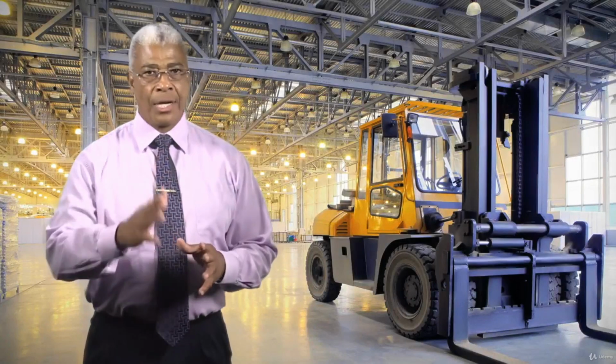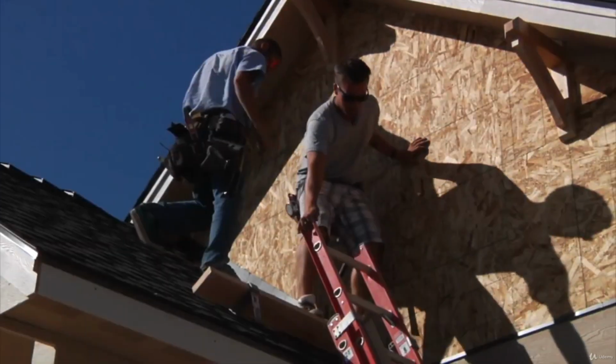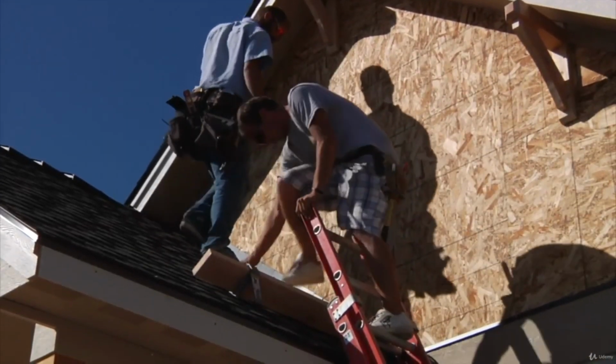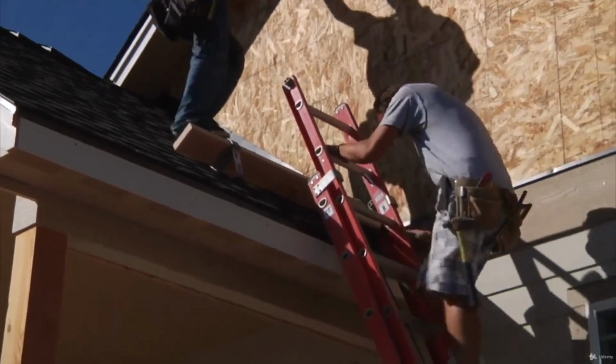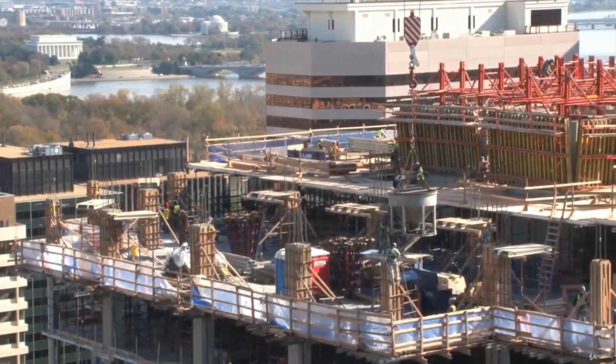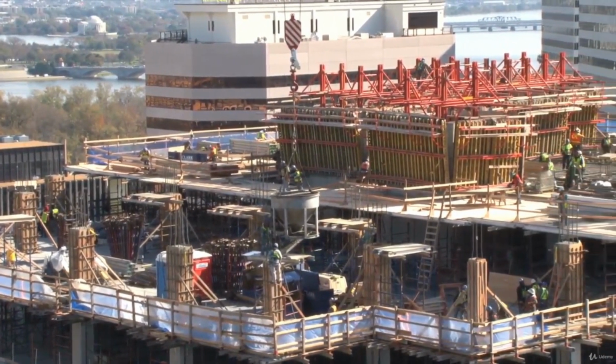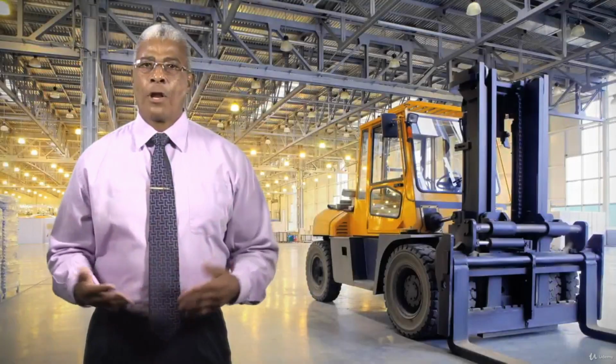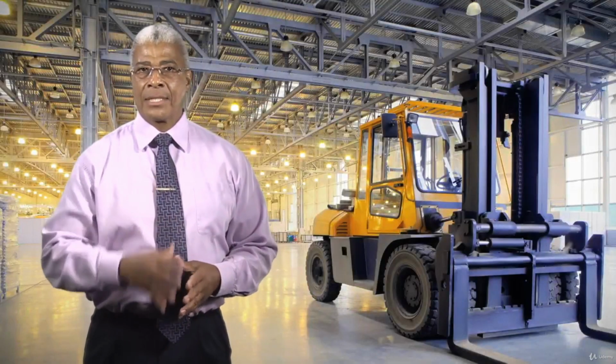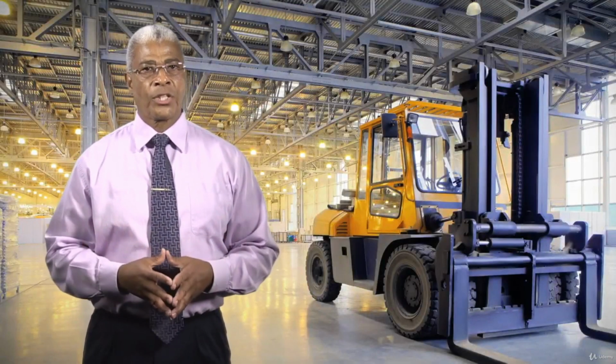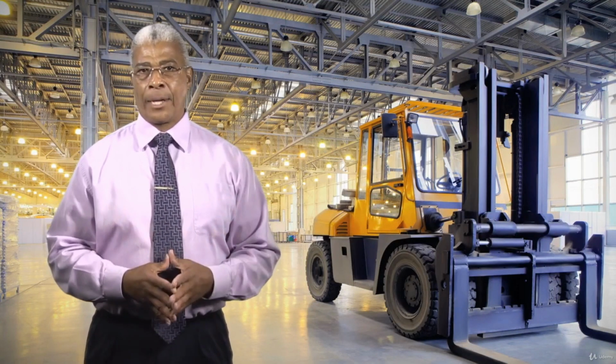Fall protection should never be ignored or taken for granted. Anytime an employee can fall 4 to 6 feet onto a lower level, OSHA requires that employers provide fall protection. Fall protection can come in the forms of guardrail systems, personal fall arrest systems, and safety net systems. Sometimes fall protection plans must be made. These must identify the locations where conventional fall protection methods are not able to be used, and then set up controlled access zones and any needed monitoring systems.